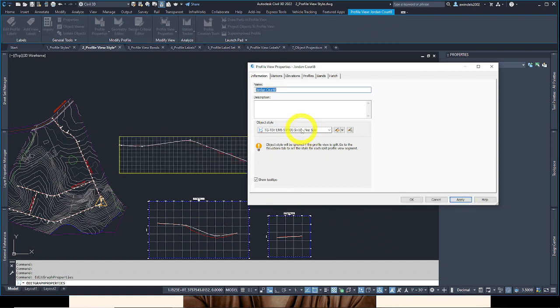Some of them are more in the vertical exaggeration, so this is the Y direction, the elevation. These oftentimes are exaggerated in the vertical or stretched. A 10 times vertical exaggeration would be stretched 10 times with respect to the y-axis, the stations, excuse me, the x-axis.